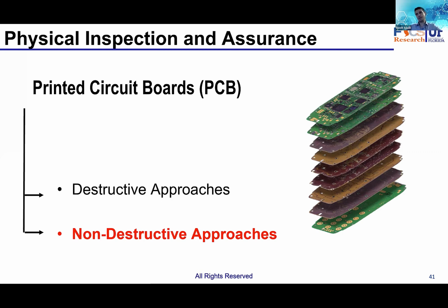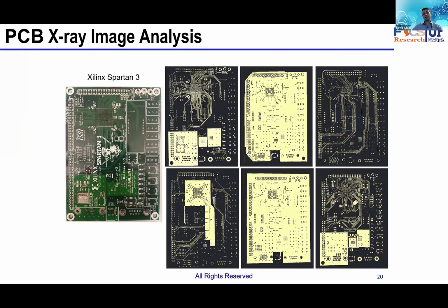Back in 2015, we published a paper on how with X-ray imaging, one can extract all the traces of a PCB. So 5, 6, 7 layer PCBs, where the number of layers really doesn't matter when we talk about regular tomography. These X-ray imaging techniques and sources, again, are coming from the medical domain, the same way a CT scan machine works. The X-ray machines are working as well. Of course, the power is different. The way the sample is mounted and the spin is different. But the noise is very much different. We don't get a lot of noise in medical applications because X-ray inherently is getting a lot attenuated when we have high Z material.